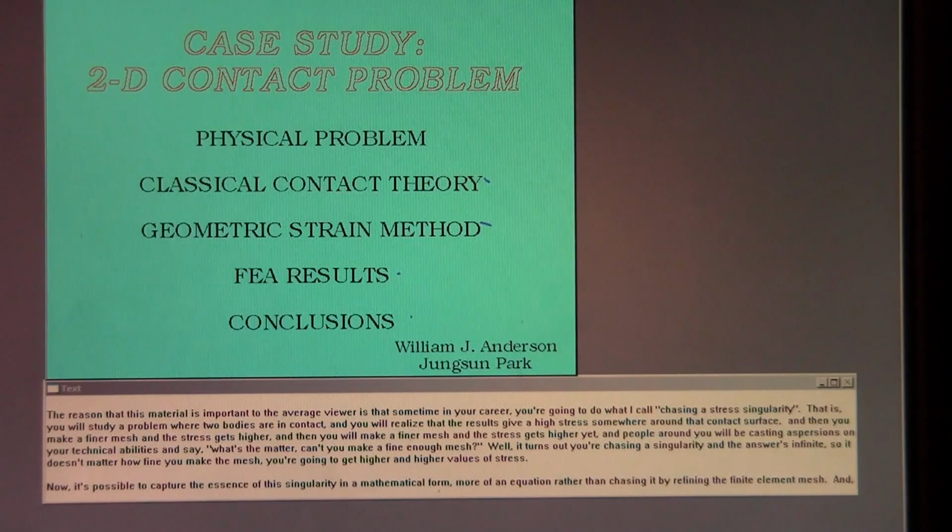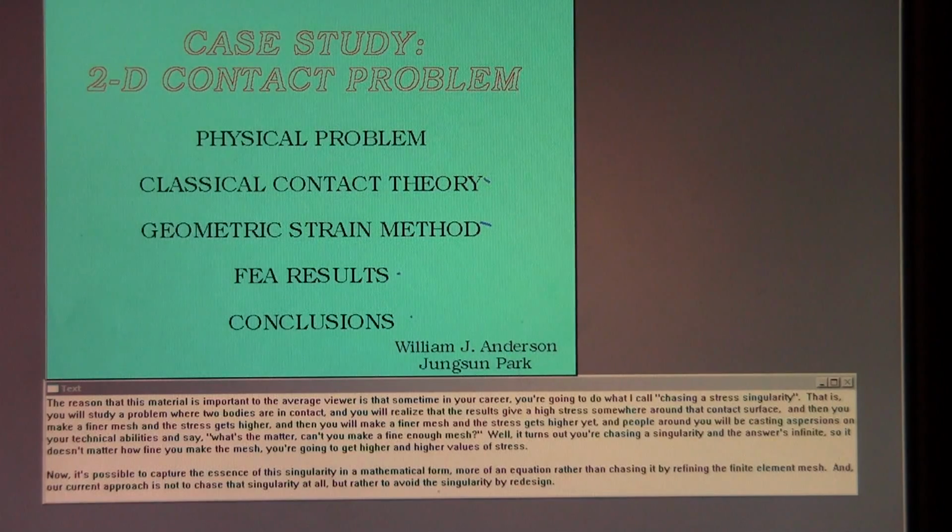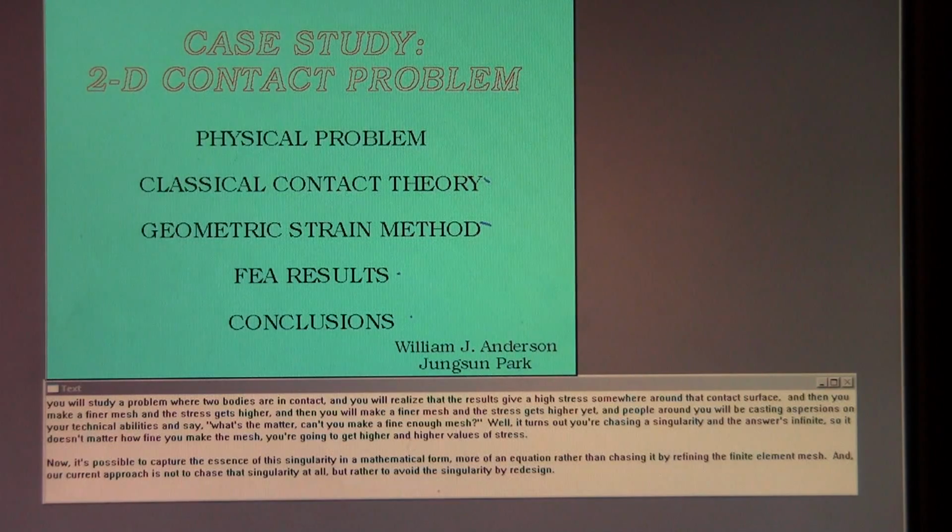Well, it turns out you're chasing a singularity and the answer is infinite. So it doesn't matter how fine you make the mesh. You're going to get higher and higher values of stress. Now, it's possible to capture the essence of this singularity in a mathematical form, more of an equation rather than chasing it by refining the finite element mesh. And our current approach is not to chase that singularity at all, but rather to avoid the singularity by redesign.